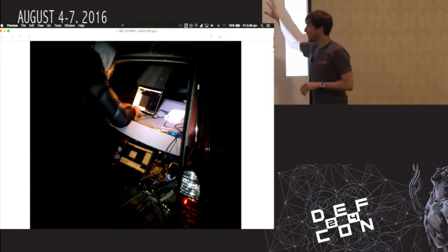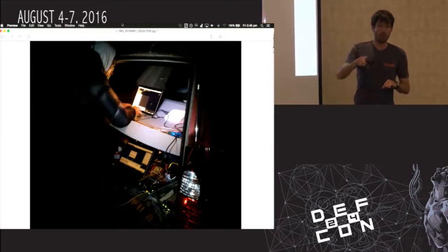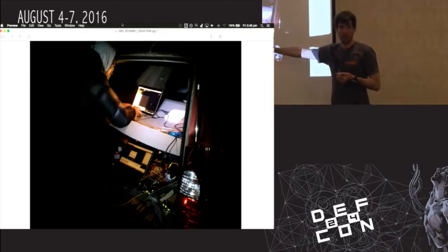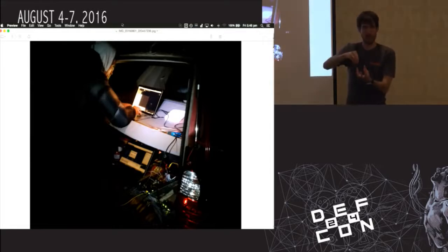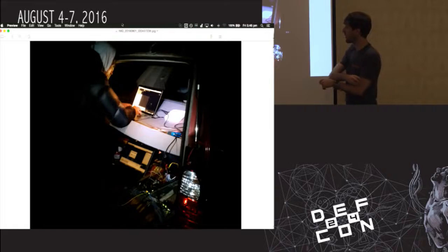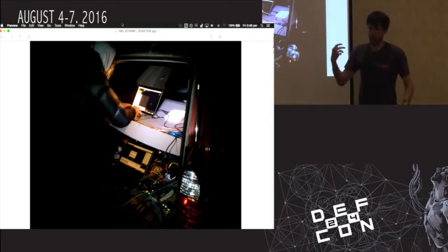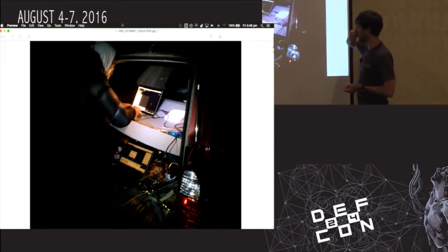As it turned out, we had to do this entire operation purely off battery power, no inverters. I had some DC to DC inverters to power the USRP, and when we turned it on, the spectrum just went to junk. We ended up getting these lantern batteries and using those, ganged in parallel, to power the USRP. The laptops just ran as long as they could on the internal battery power. Unfortunately, because they're MacBooks, you can't just pop in another battery, not that you could exchange the battery while you were recording anyway. But I got about an hour's worth of recording on that, which is pretty good.